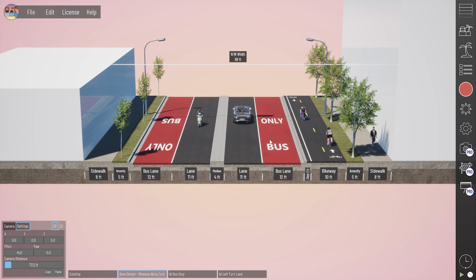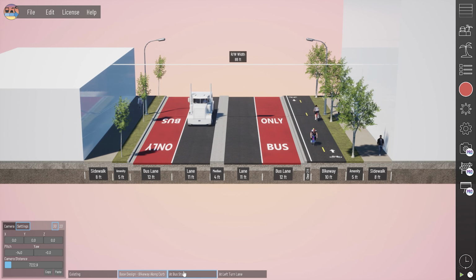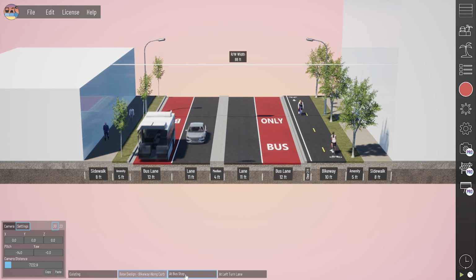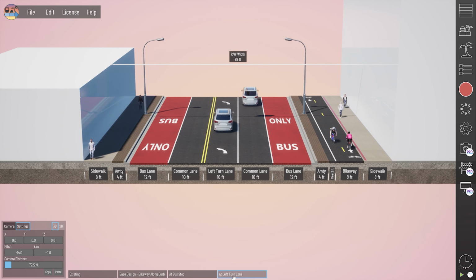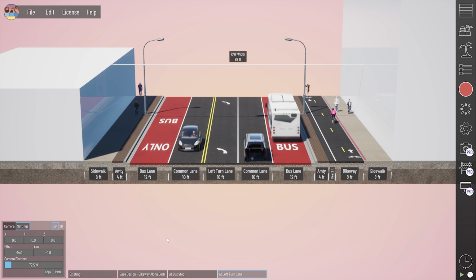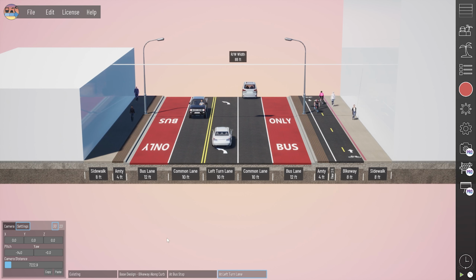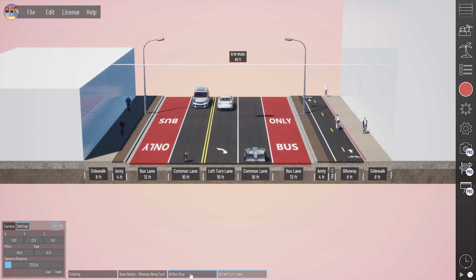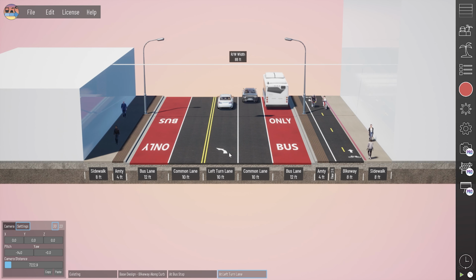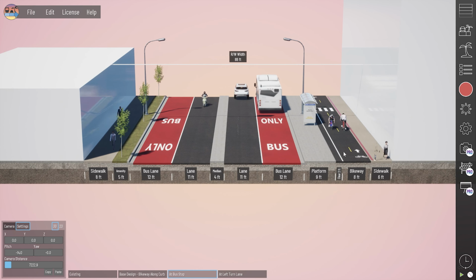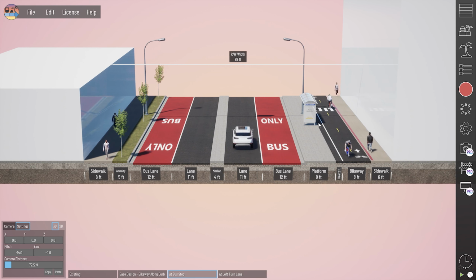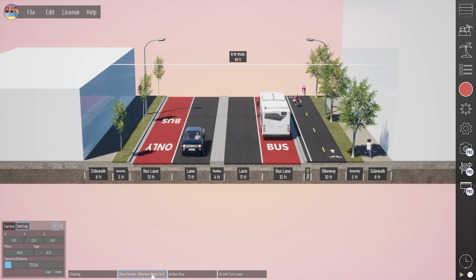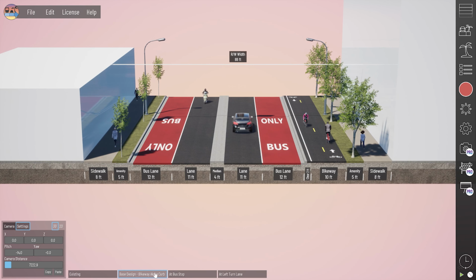And what I wanted to do with the phasing here was to show how a base design might differ in a corridor like this at a bus stop or at a left turn lane, where your general design isn't necessarily changing. We're not evaluating alternatives or showing construction staging, but in certain areas where you might need to widen out the road for a turn lane or to accommodate a bus shelter and platform, how the rest of that roadway might need to change outside of that base design.